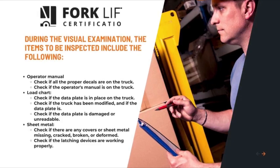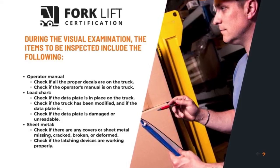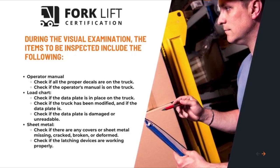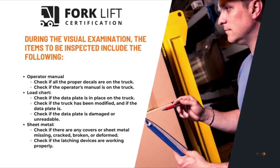During the visual examination, the items to be inspected include the following: operator manual. Check if all the proper decals are on the truck. Check if the operator's manual is on the truck. Load chart. Check if the data plate is in place on the truck. Check if the truck or data plate have been modified. Check if the data plate is damaged or unreadable.